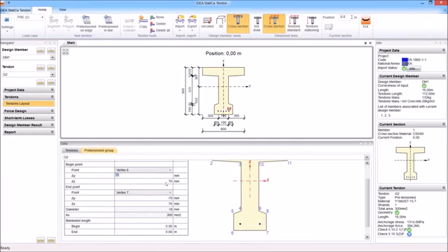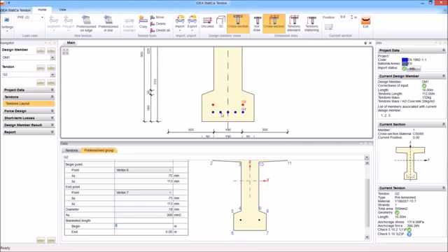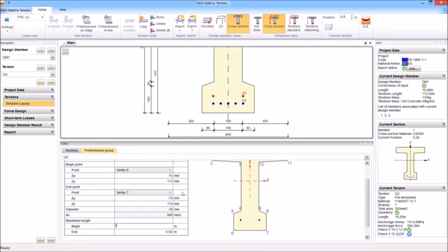We will add one pre-tensioned line, and the number of strands will be again 2, but the geometry will be different. Here I will have again 75, 113, minus 75, and 113. And now it's okay. You can see this group.